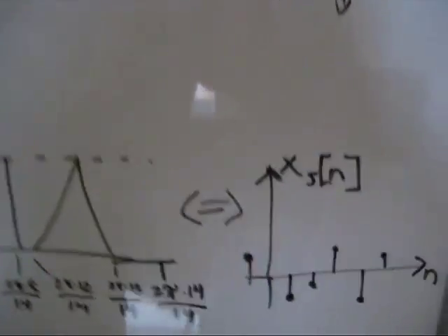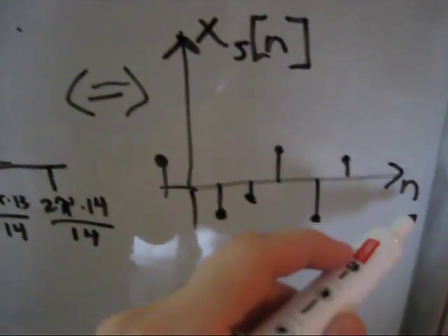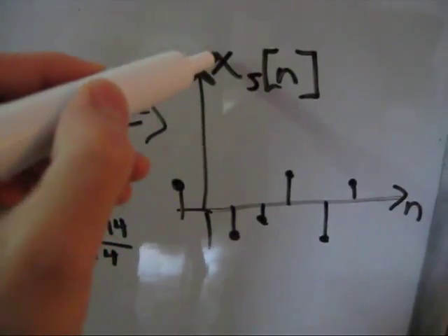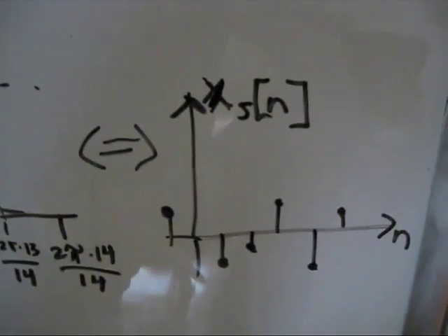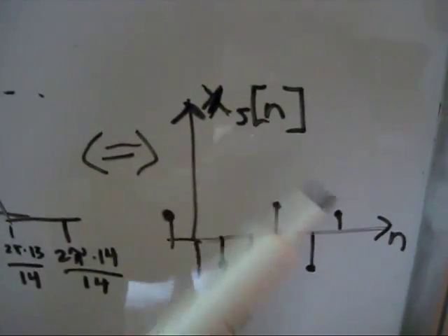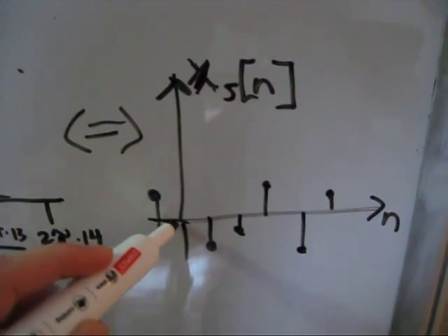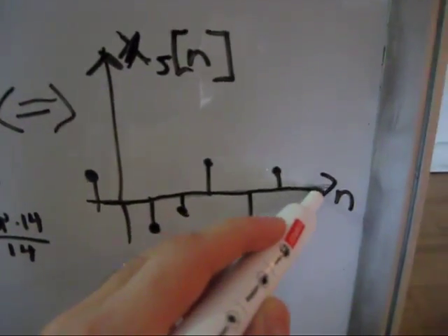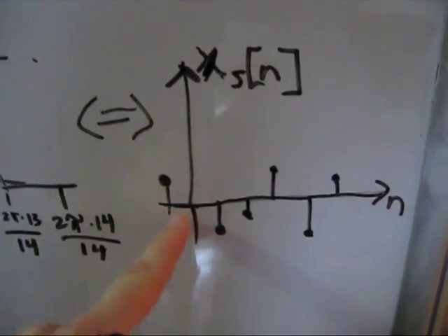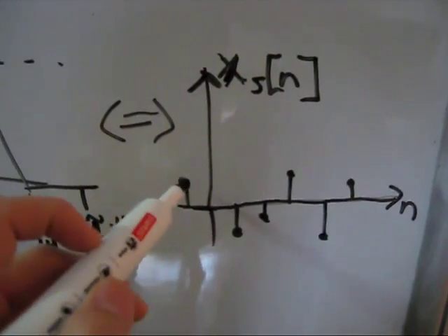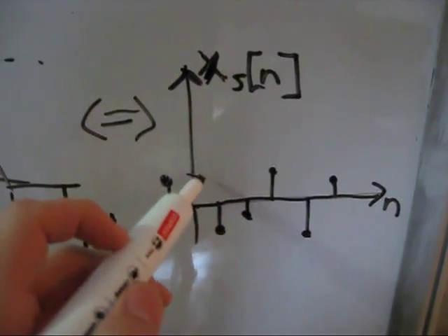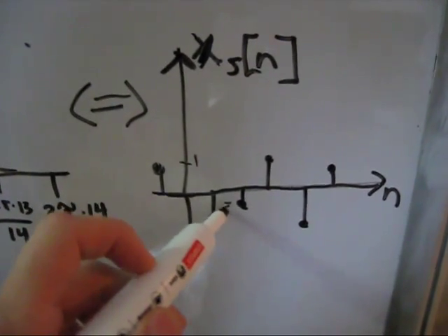So after you've done everything with the Dirac Comb, we're going to go down, and now we have our actual sampled signal. So this is now sample number instead of time, and this is our discrete sampled signal. Now we're using square brackets to denote that it's a discrete function instead of a continuous function. This is now actually what you would have inside your computer, inside your microcontroller, inside your memory, where now we have our actual sampled values. This is going to be like 1, and this is going to be like 0.5 or something.